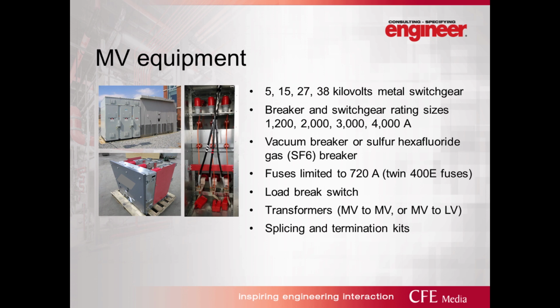There's really two types of breakers being used nowadays. The air breakers are kind of being limited to high voltage. One is the vacuum breaker. It's basically where the contact assembly or the arc is extinguished in a vacuum tube. The other is the sulfur hexafluoride gas, or the SF6. This is where that same contact assembly is now flooded in a container full of the gas, and that helps to extinguish the arc. The lower picture on the left is the vacuum breaker.